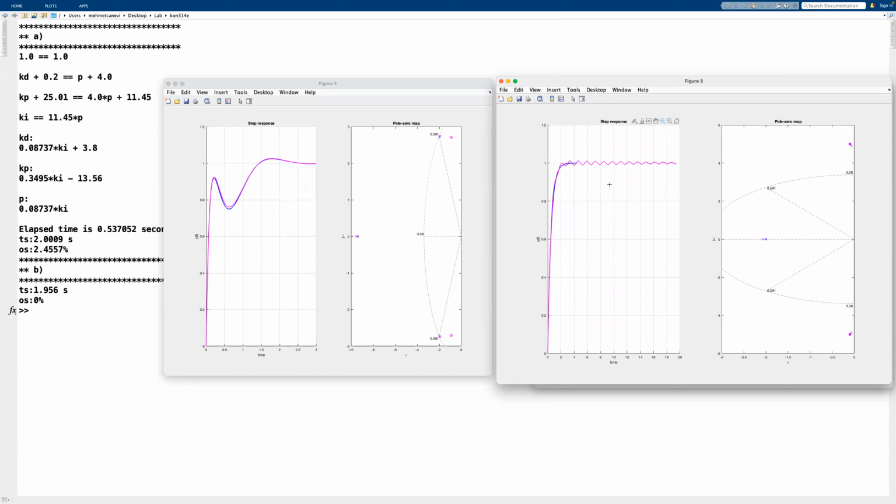This is also important because pole zero cancellation on the right half plane is not acceptable at all for the same reasoning. The pole zero cancellation might not occur on top of each other, and then you would have instability in your closed loop. That is not something that we want. And the same goes for here. If you're near the j omega axis, you should be again careful with your cancellations.